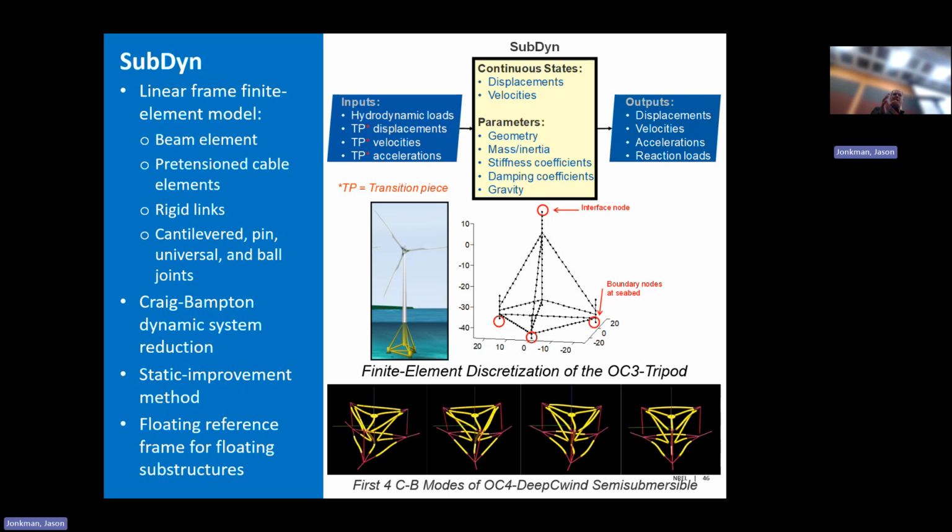If you use SubDyn for floating systems, the 6 Guyan modes are basically the rigid body modes of the substructure, and they follow these floating reference frames. Whatever ElastiDyn does, they follow along. And then the Craig-Bampton modes are like the internal elastic modes relative to that frame. And again, as of 4.0, that now supports full large motion. So roll, pitch, yaw are all large rotations.